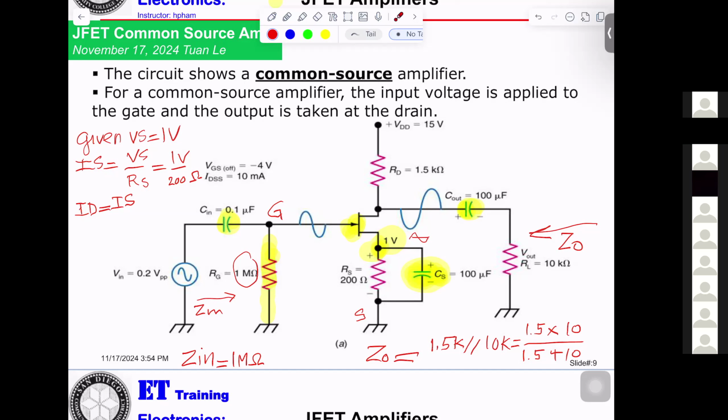Tell us why, Mr. Pham. That will be telling you one thing. Your voice, that's an AC signal coming in. If you get a high input impedance, you don't lose your signal. The other amplifiers do not get a high input impedance. That means they get a voltage divider or whatever, so your signal coming in has to be divided. They don't want that.